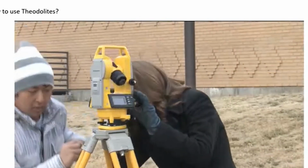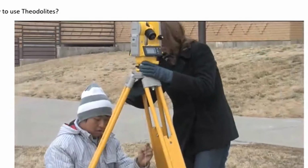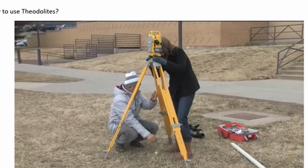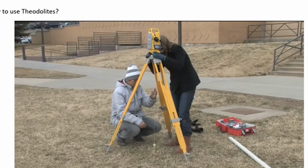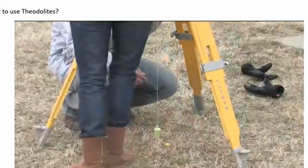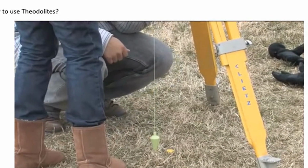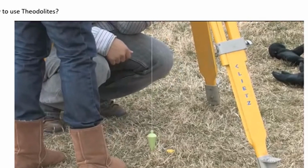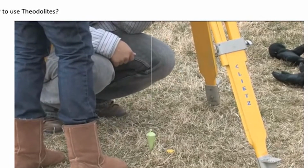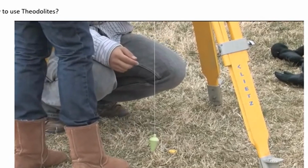Once the height of the tripod has been made comfortable for the team, it is important to make sure that the instrument is directly over the traverse cap. To do this, place the line of the plumb bob through the hook in the bolt of the tripod. Then gently extend the plumb bob line down towards the top of the traverse cap. Observe the location of the tip of the plumb bob. If the tip of the plumb bob lines up directly with the center of the traverse cap, you're done. If not, adjust the theodolite's location on the top of the tripod accordingly until the tip of the plumb bob is directly centered on top of the traverse cap.